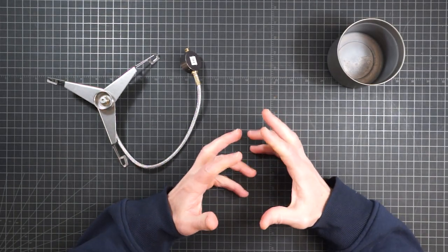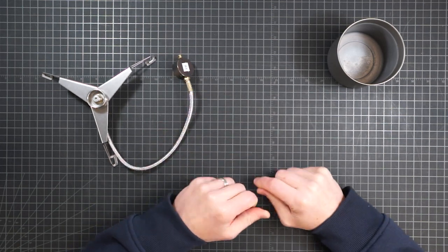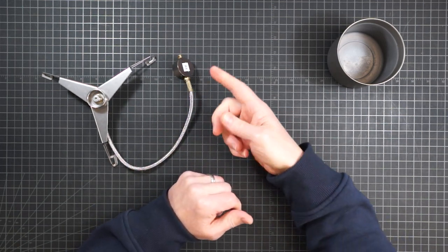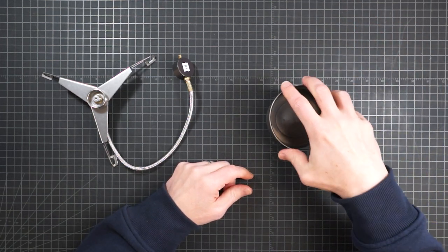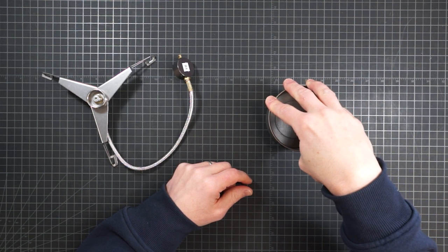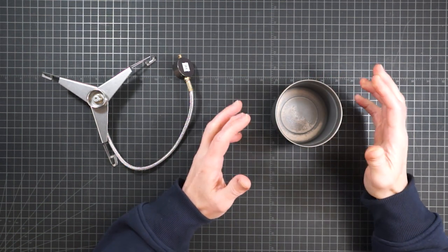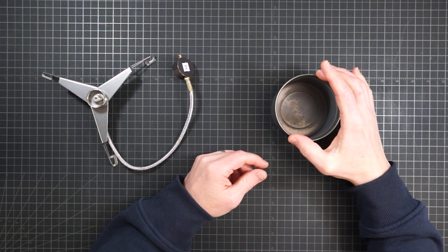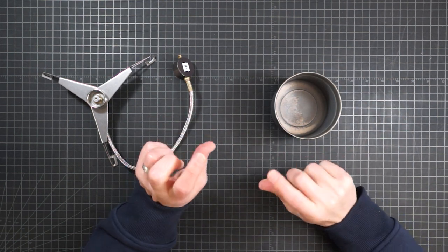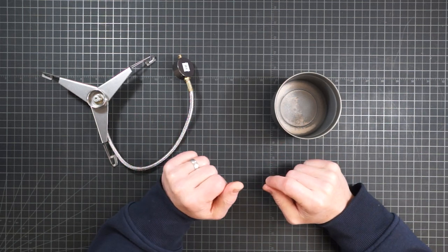The best way I can describe trying to work with this cursed valve is by likening it to a rubbery interface, probably due to the seal inside. So when attempting fine adjustments, it gives before moving and then unsticks and launches forward more than intended, making it impossible to simply increment slowly until set. And aggravating all of this is the fact that the valve's highly sensitive in this range. Tiny rotations have big consequences.